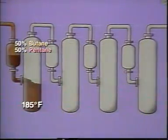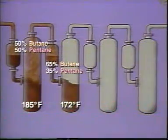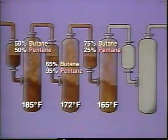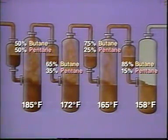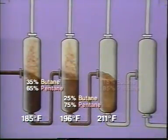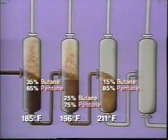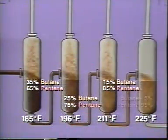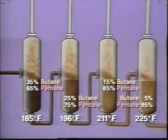We used a series of stills to demonstrate how a mixture can be separated by distillation. The top stills operate at progressively lower temperatures, so fewer heavy components are vaporized as we progress up from one still to the next. This eventually isolates a light fraction in the top still. The bottom stills operate at increasingly higher temperatures, so more light components are vaporized out of the liquid as it is piped down to each lower still. This forms a heavy fraction in the bottom vessel.